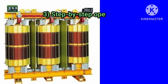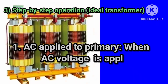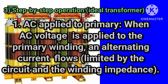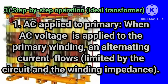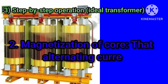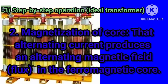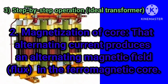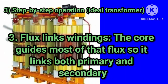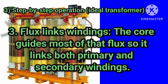3. Step-by-step operation, ideal transformer. 1. AC applied to primary. When AC voltage is applied to the primary winding, an alternating current flows, limited by the circuit and the winding impedance. 2. Magnetization of core. That alternating current produces an alternating magnetic field, flux, in the ferromagnetic core. 3. Flux links windings. The core guides most of that flux, so it links both primary and secondary windings.